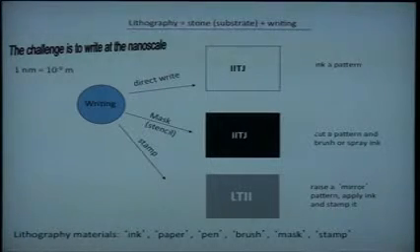And another way is to actually create a stamp with replica feature like this, and you pick up the ink only in these regions and stamp it. When you stamp, you will be passing on the ink which is coated on these raised impressions onto the substrate, and that's how you create a given pattern. I can't think of anything different from these three principal modes of writing.